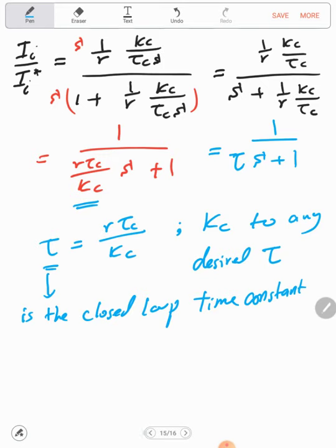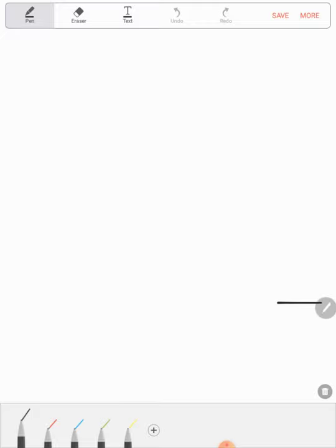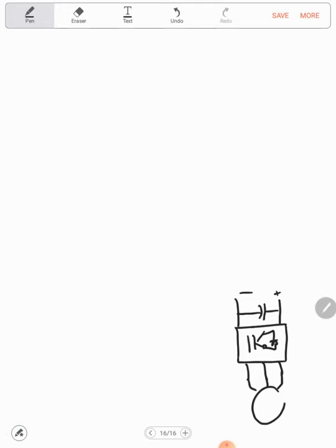So simply now we can plot the block diagram of the vector control for the permanent magnet synchronous machine. And for that, the first thing here, let's assume that we already have the power circuit. So this is the DC link, and here this is the inverter, and the inverter is feeding the permanent magnet synchronous machine.